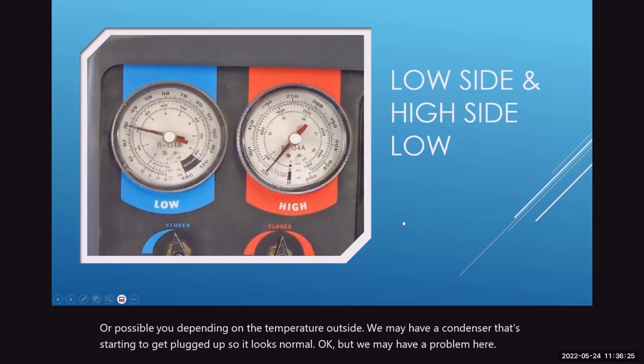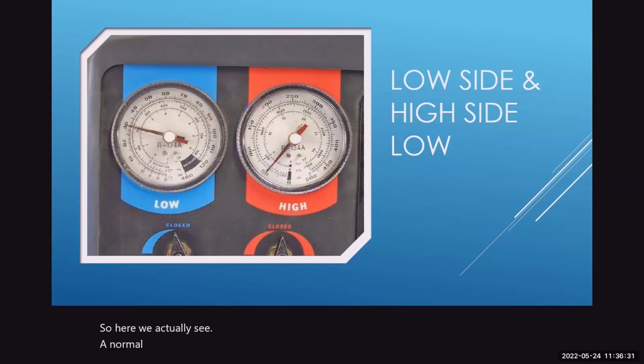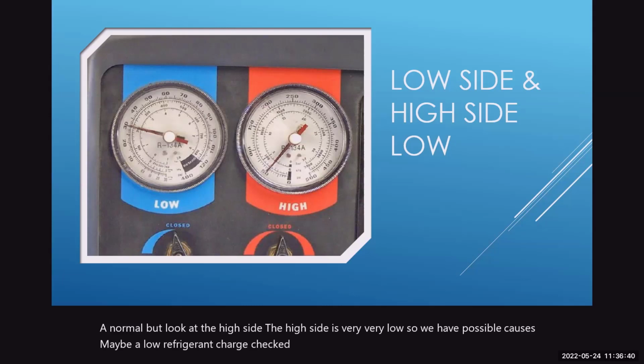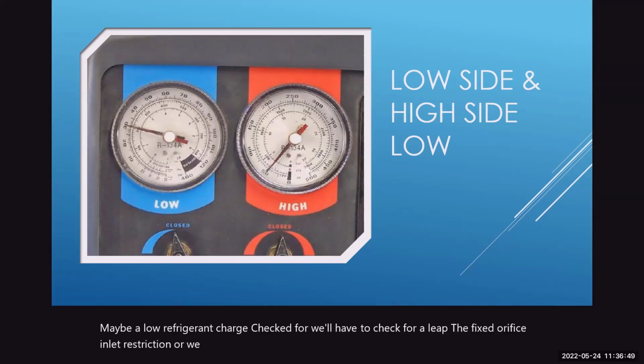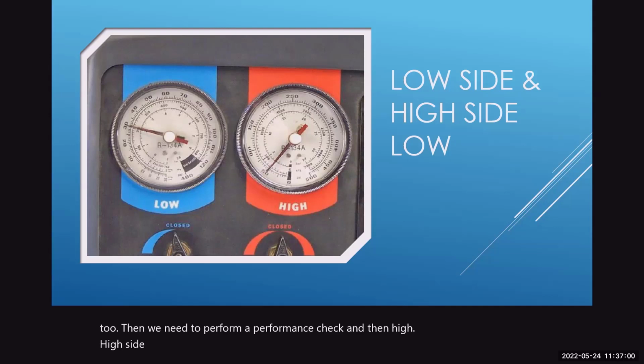So here we actually see a normal low side, but look at the high side. The high side is very, very low. So we have possible causes: maybe a low refrigerant charge, and we'll have to check for a leak. The fixed orifice inlet may have a restriction, or we may have an expansion valve that's not working. Then we need to perform a performance check, and then high side restriction performance tests, drop tests like that. So we're going to look at the temperatures to see what's going on.